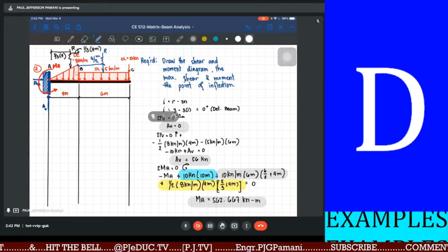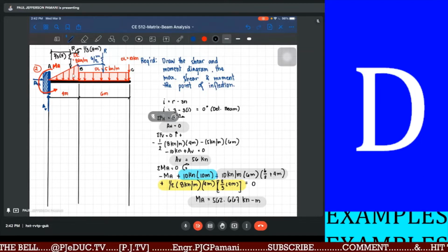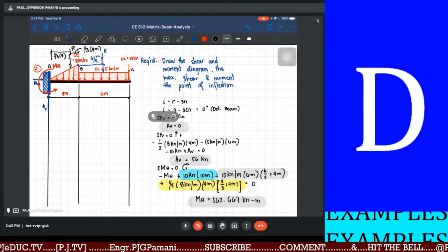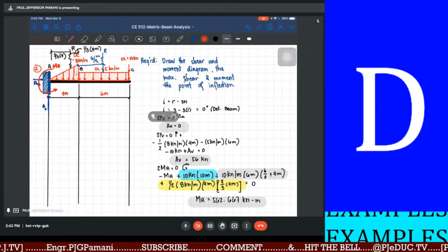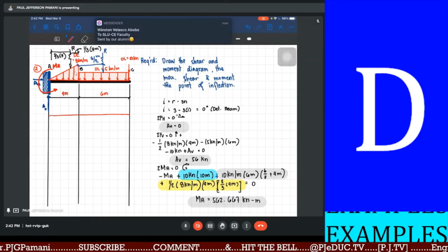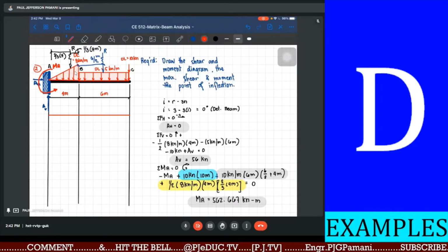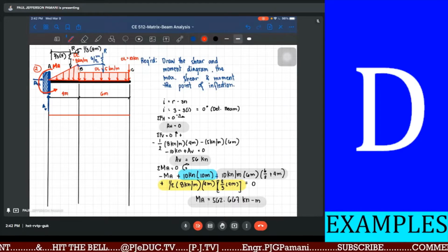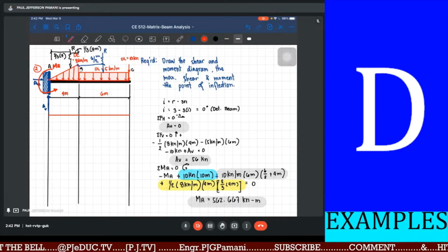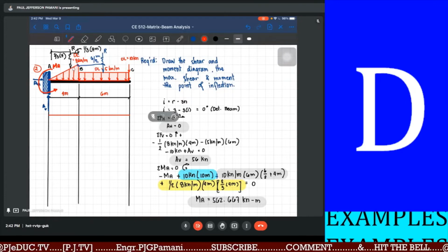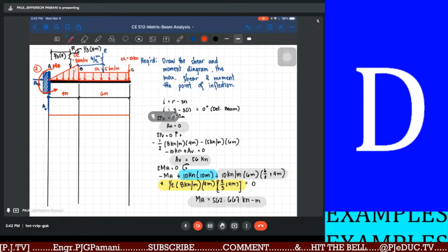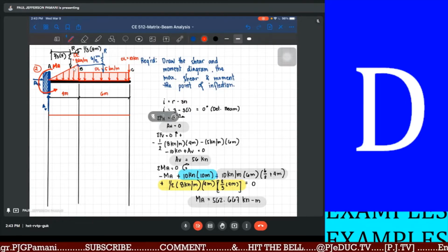the maximum moment. There is another type of diagram that you need to include here, which is your normal diagram. Normal diagram represents the actual force applied on our beam. Okay, actual force or the horizontal forces. But most of the time, actual forces are then applied to a frame structure.